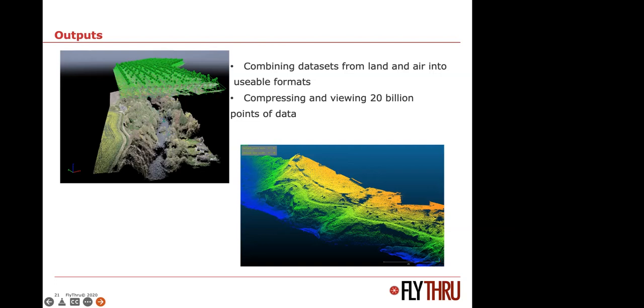And looking at it from a slightly different angle, the LiDAR imagery, which is the other image, which starts with the orange working down to the blue, is the same area of land from a different direction. What we've done is we've asked the software to remove the vegetation and give us a 3-dimensional point cloud. We have colorized that by the intensity of the return back to the LiDAR system. So obviously it was nearer where it's orange and further away where it's blue. And that creates our 3D model.